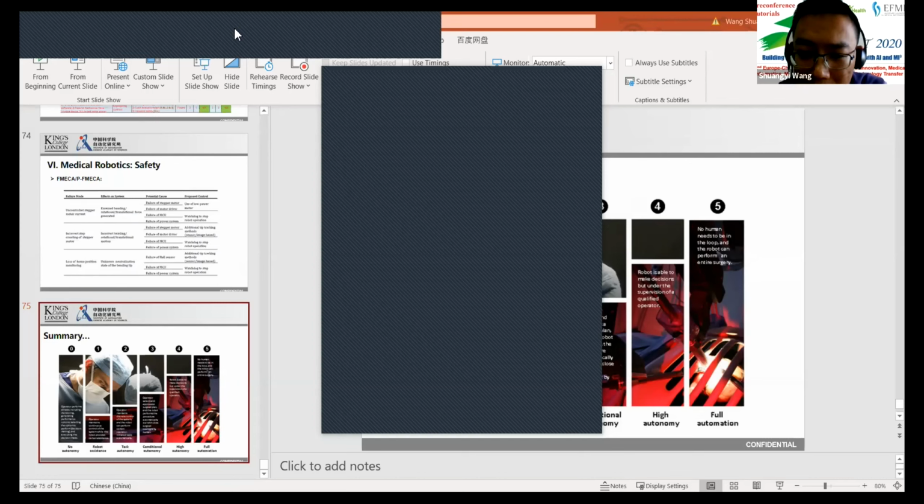Also, you can look at the smoothness of the trajectory and the amount of force you can exert, like what I mentioned, whether this is force control or hybrid control, both force and position, where you can apply a certain force and also reach the position at the same time. This could be another metric. And apparently it's also the accuracy: if you pre-plan the surgical path, how accurately can the robot achieve it? And also the reaction to patient motion.